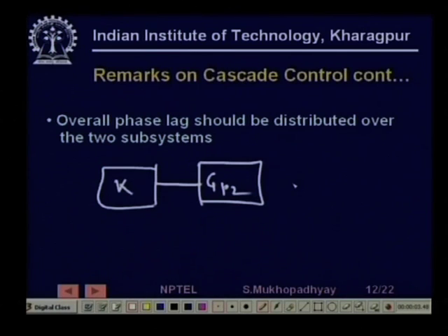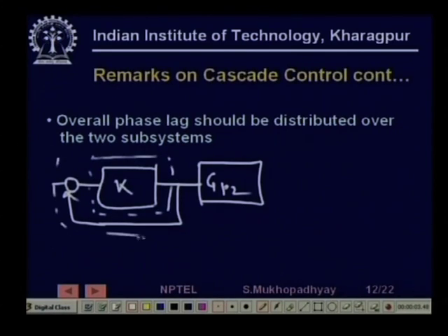Then what is the idea of giving a feedback here? The loop gain of the open loop plant and the loop phase of the closed loop are the same, because both are constants. So, the problem of loop phase still remains and the whole problem will come in the outer loop. So, it is becoming like the old case.